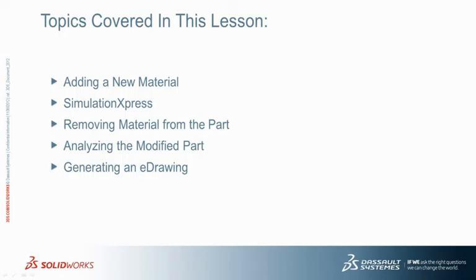In this video, you learned how to create a new material in SOLIDWORKS, apply it to the windmill base, and then use Simulation Express to conduct stress analysis. You then removed some of the material from the legs of the base and conducted the analysis again. You also learned how to generate an eDrawings report to share your analysis results more easily.